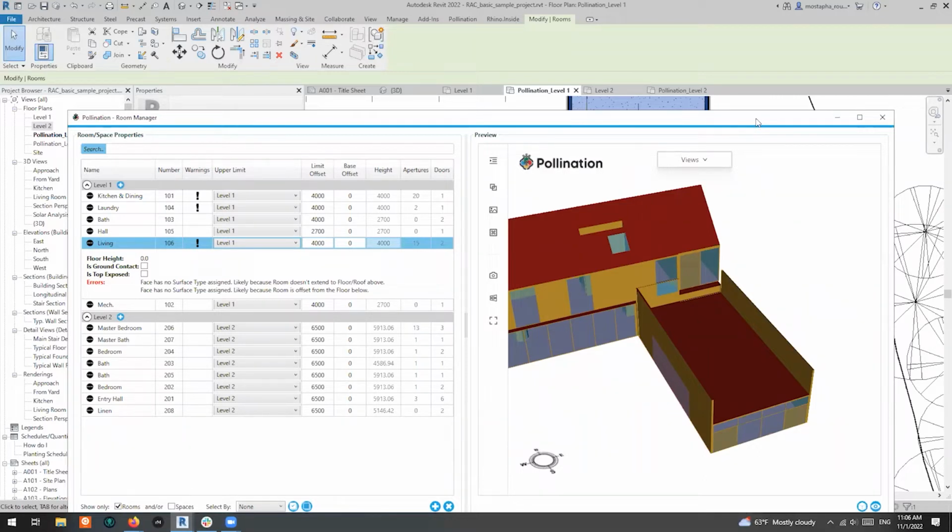There's probably a million reasons why. So whenever it's on that exterior wall, it always causes an issue with apertures, as you mentioned. Is there another workaround for that? Like if you move the separation line outside the wall, can it pick up an aperture? Yes. As long as it touches the wall, it picks up the aperture.